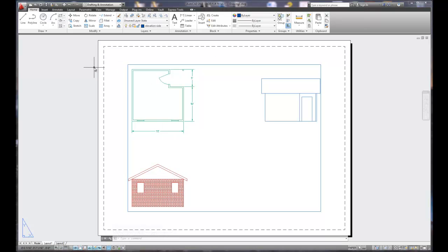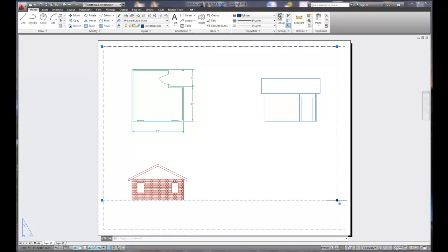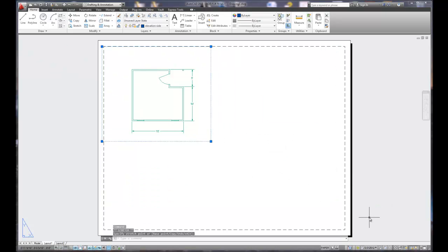We have our drawing sheet. It's 8.5 by 11. Have the printable area. Have the viewport. Well, the key thing with the viewport is that I can make the viewport about the same size as the printable area. And that way I can work with it. So what if I had multiple viewports on one page? So if I took this viewport and shrunk it, well, we know that there's 2 other views there, right?